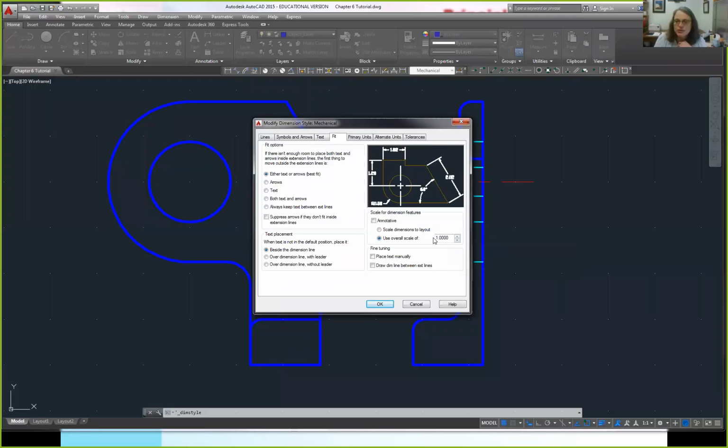In this example, we are just going to use a scale of 1 because our drawing will fit on a standard size piece of paper. If, however, we want to print it bigger, we would need to change our scale. You can allow AutoCAD to adjust that scale automatically depending on what page layout you choose, and we'll talk about that later. For now, just set everything up as indicated on the text, starting on page 34. Okay?